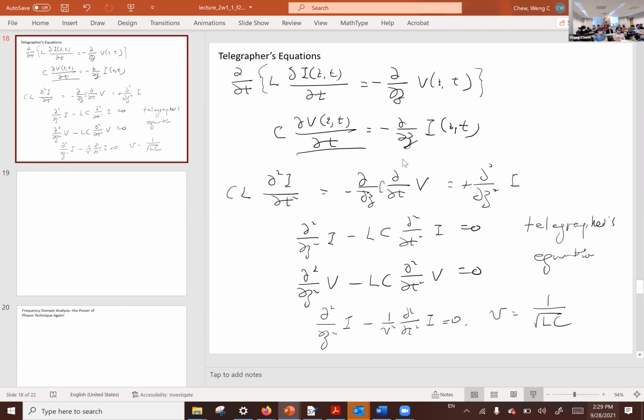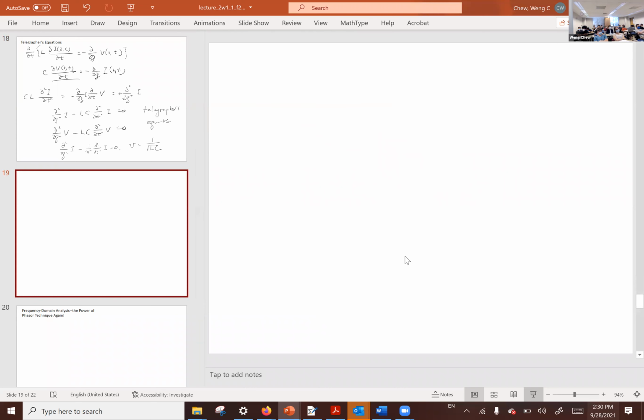Okay. I think most of you have had transmission line theory before, am I right? For those of you who have not, you don't have. Okay. But so far, I think you can follow it. It is very similar to wave theory, except here is where it departs from wave theory. Instead of having a relationship between E and H, we have a relationship between V and I. And that relationship is the characteristic impedance.